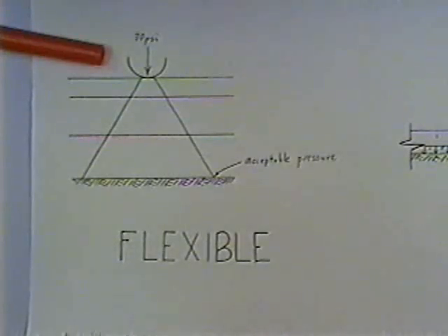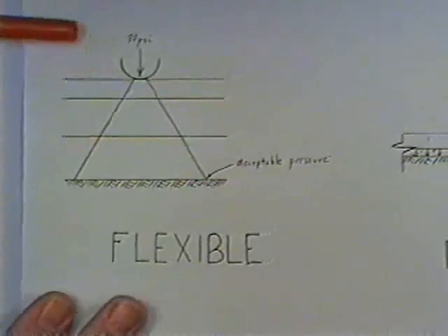You can see that those downward forces spread out as they move down towards the subgrade that's supporting the pavement surface. Those are the different layers we just talked about: the surface, the base, the subbase, and we're designing those thicknesses so that they exert an acceptable pressure on the subgrade.